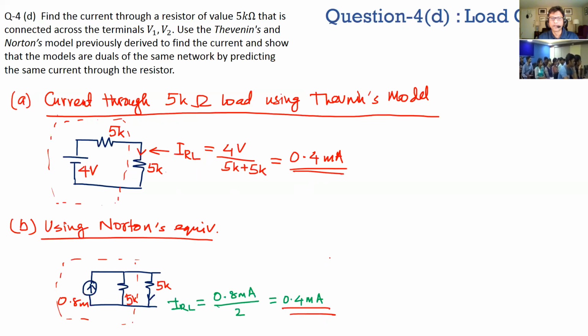So for a network, you can find either a Thevenin's or a Norton, but for some circuits, usually a Norton is better than a Thevenin's. For example, if you have a common source amplifier like this, and you have a network here, it's better to find a Thevenin's network because this impedance is infinite looking into it. So you want to look here as a voltage source.